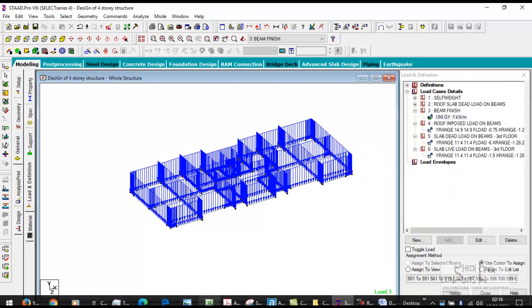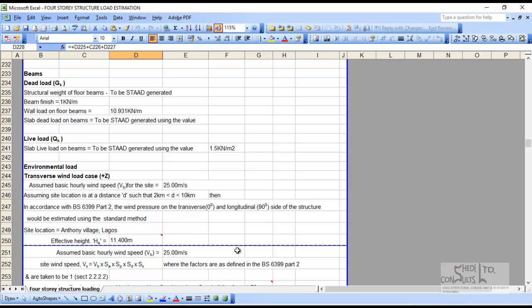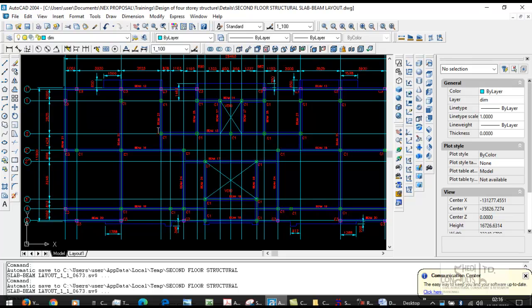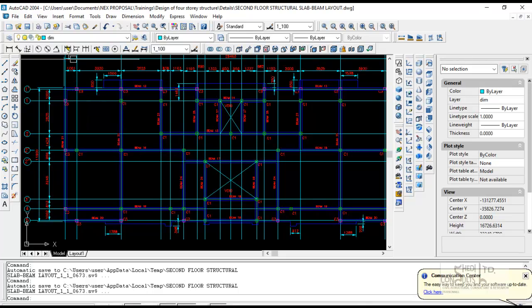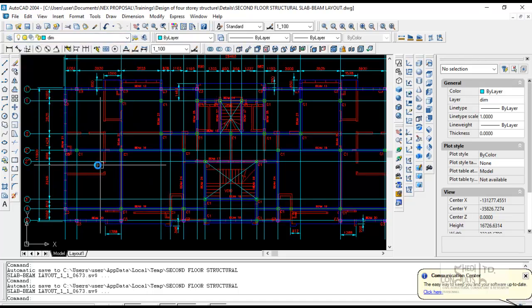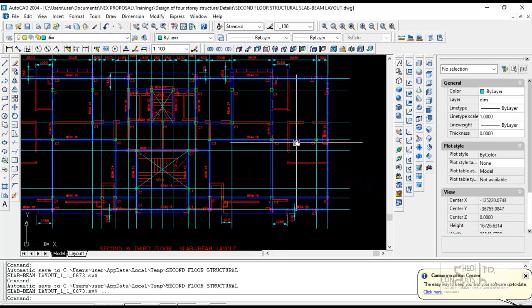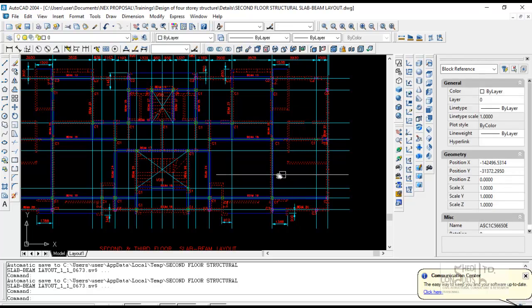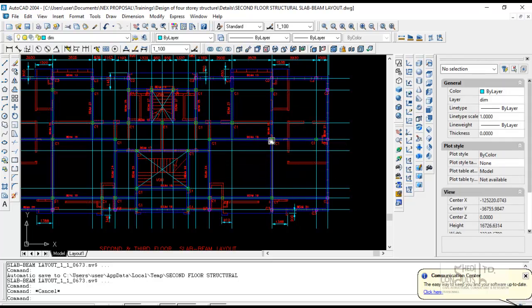Great. The beams are also carrying wall partitions. Very important. Look at it here. Wall partition, wall load on floor beams. So we're going to assume that all the beams, if you look at the architectural design, it will show you which beams are carrying loads. But one of the issues with residential structures is that sometimes the client may change the intention and add additional walls.